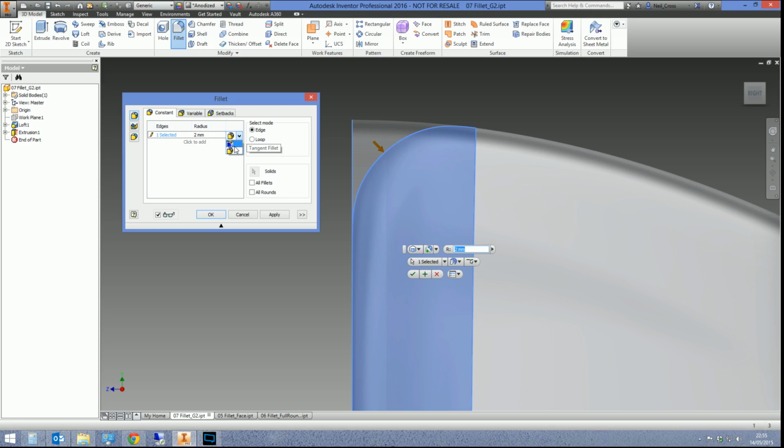No. Of course you don't. If you do metal brackets and you just want to get rid of an edge, you don't need this. This is mainly for people that work in product design, plastic parts, consumer products. When those guys need more aesthetically pleasing designs, then they would be interested in the likes of the G2 fillets. But us working with metal and big frames and fabrications, you couldn't give a monkey's. But it's good to know what it is.